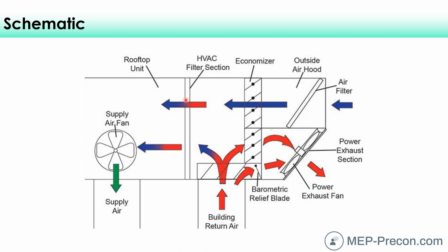And then there's a coil in here too, and there's a compressor and a condenser, and all the components of the refrigeration cycle would be in here if it's a packaged air handling unit. But anyway, let's just look at the outside air and the exhaust air streams here. So the outside air comes in and it mixes with the return air. Now, a packaged AC unit does a pretty good job of trying to relieve the amount of air that comes in.